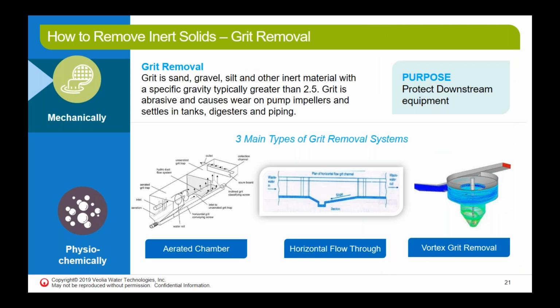Moving on from the coarse solids, now we will be talking about solids that are still fine, so fine that applying coarse screens is not going to be practical, but they're also heavy enough to be easily separated with gravity. And usually in these cases, we're talking about grit. So we're talking about silt and sand particles that are heavy enough that they would settle quickly.